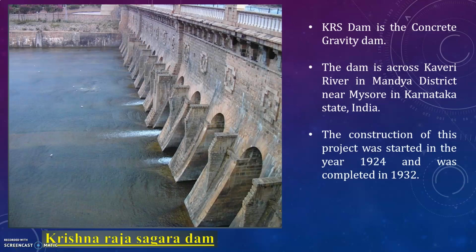They are particularly suited across gorges having very steep side slopes where an earth dam, if constructed, might slip. Gravity dams are well adapted for use as an overflow spillway crest. Earth dams cannot be used as overflow dams. Due to this, gravity overflow dam is often used for the spillway feature of earth and rockfill dams.